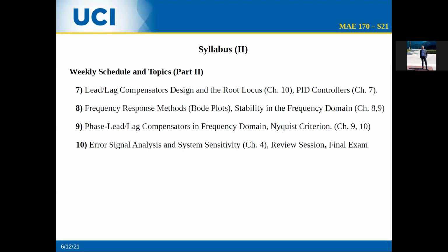What is a harmonic function? Well, a harmonic function is a sinusoidal function. So it's just a pure sine or cosine, or a linear combination of sines and cosines. And when the input is of that kind, then we can study the output of our system using the Bode plots, and then the Nyquist plot will introduce the Nyquist stability criterion.